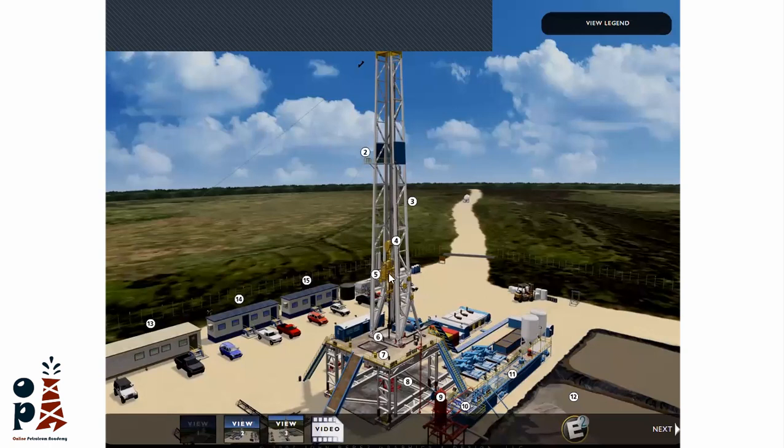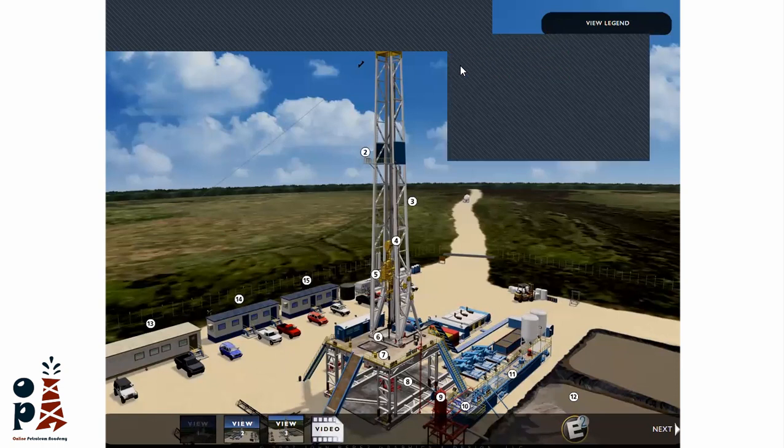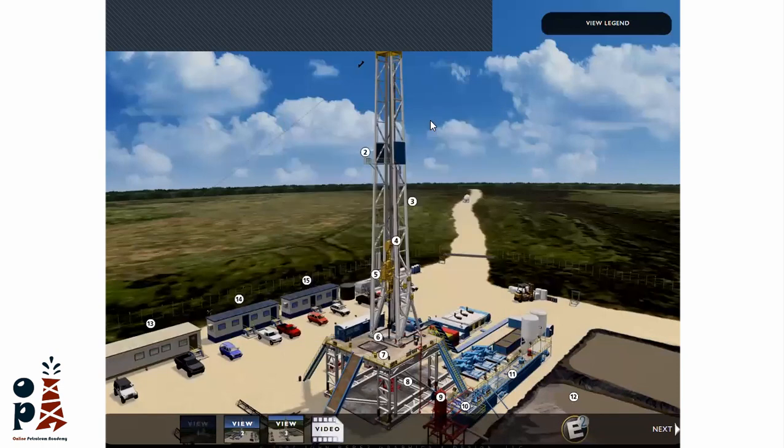Here you see the top drive, and the top drive is very important. Maybe 15 or 20 years ago we were not using the top drive, but we were using the Kelly, which is still used today but very rarely, because the top drive is a very powerful tool. We can make a connection of 3 joints, not only 1 joint. With the Kelly operation we used only 1 joint, so it took time to make a connection. With the top drive, we can make a connection of 3 joints, which is around 30 meters or 90 feet, and the drilling is faster than the Kelly operation.